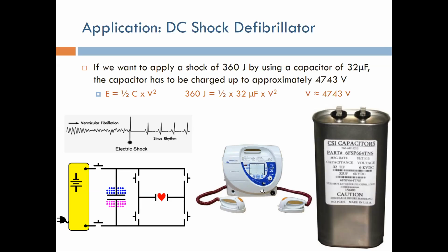One very important thing I want to give you an idea about regarding this capacitor. This capacitor here can be charged with almost 5,000 volts, okay? If you work as a biomedical engineer later, for those of you who are in the biomedical program, if you're trying to repair one of these devices, be very sure that this capacitor is discharged before you touch it, okay?